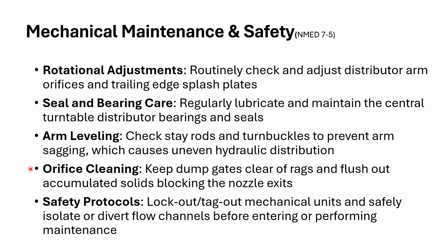Okay. You want to make sure the holes in your distributor arm and on your dump gates have no rags in there. If there's any accumulated solids, you want to flush those out. And this is one of the areas, you remember I told you about preliminary treatment or pre-treatment, one of the reasons we want to get rid of rags is they'll cause all sorts of problems downstream. Here's one of the places rags can cause a problem.